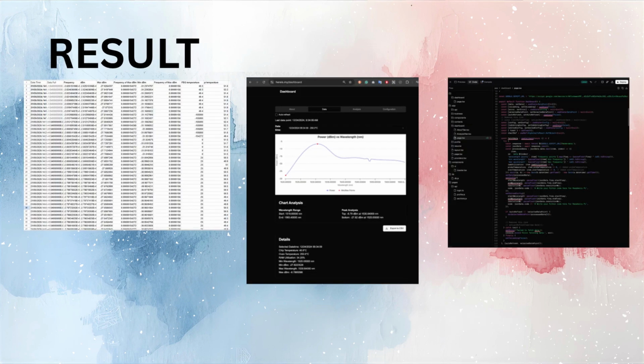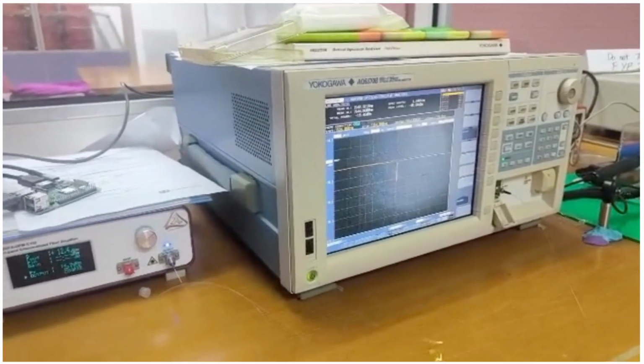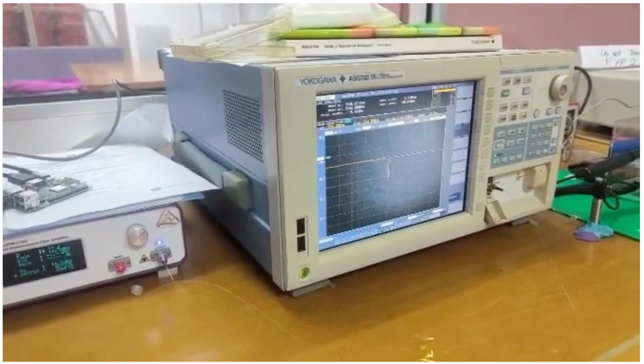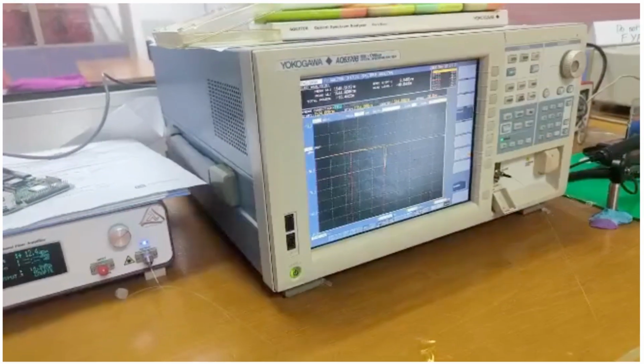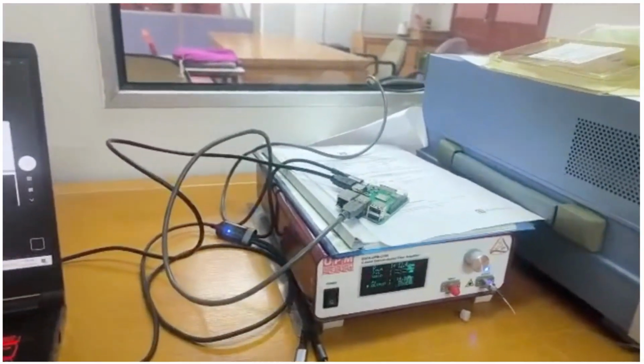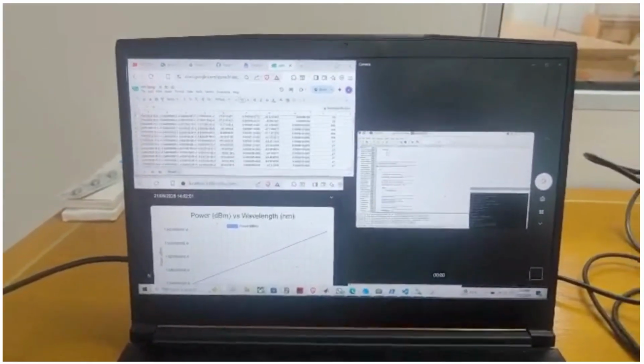These are the results, our findings. This is the FBG temperature sensor system. FBG sends continuously the temperature change, and the temperature variation is displayed on the OSA. OSA will transfer to our handphone wirelessly using the Raspberry Pi. So we can continuously check on the handphone.